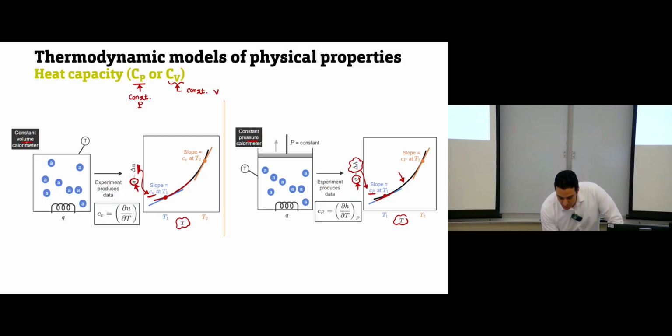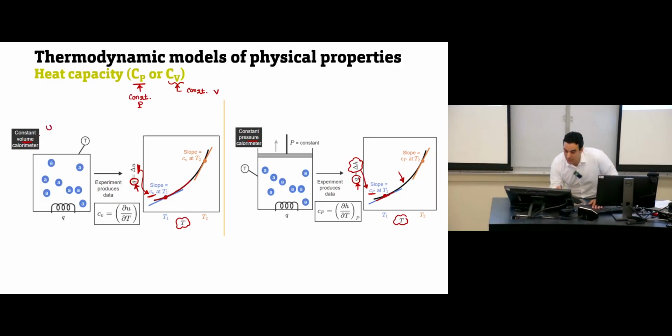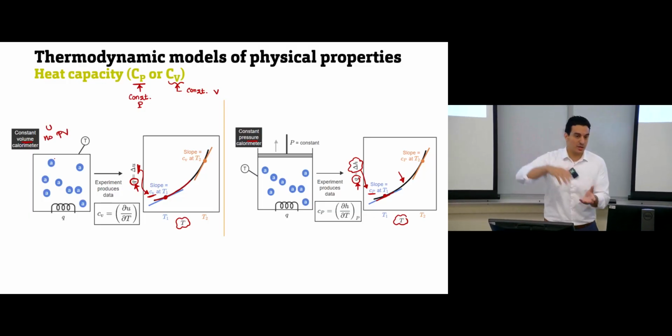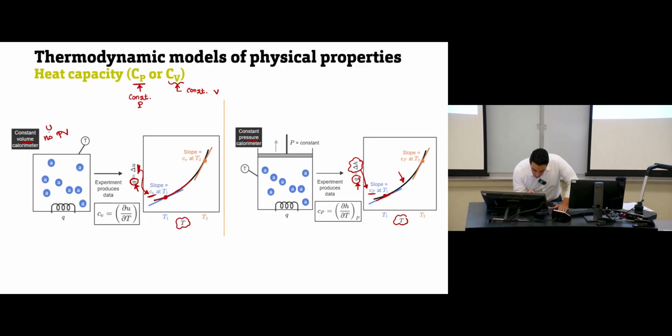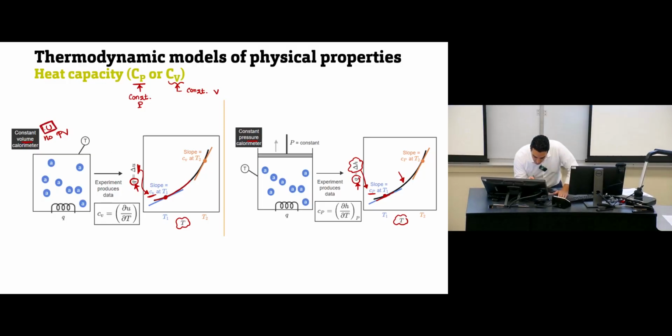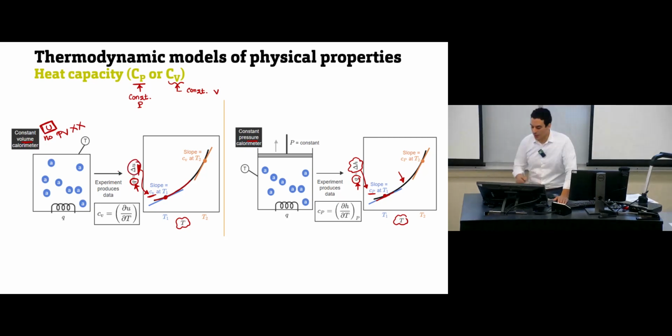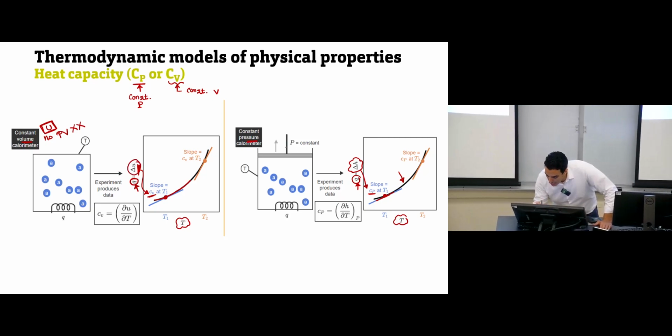Here in the system we have constant volume, we have internal energy, but we don't have flow work. There is no PV, there is no movement in the piston or in the volume. So the amount of energy or the temperature change will only be reflected in delta U. But here at constant pressure, we have the movement that can happen for this piston.